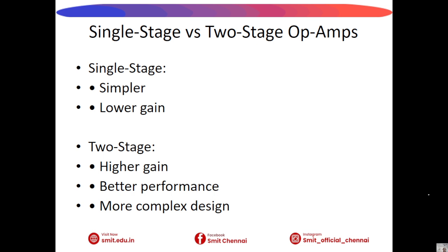Next, single stage versus two-stage op-amps. Let us compare the two architectures. Single stage op-amps are simpler, consume less power, and offer faster response. However, their gain is limited. Two-stage op-amps provide a much higher voltage gain and better output drive capability, but require compensation techniques to ensure stability. Therefore, the choice depends on the application's performance requirements.